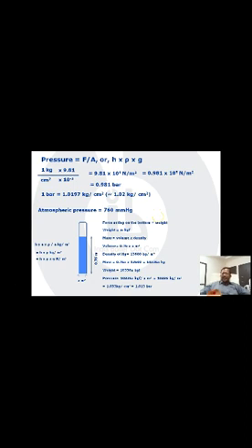The mass will have the same force as weight going down, acting over a cross-sectional area of A. Now A gets cancelled, so it remains as H into rho. So it gives you a pressure equation. If you know the height of a liquid column, the equivalent pressure is H into rho kg per meter square. And if you multiply it with g, kg will become Newton. This will become Newton per meter square, which you know as Pascal, right?